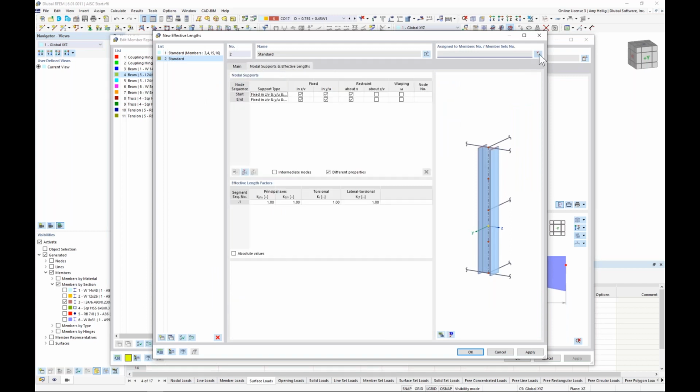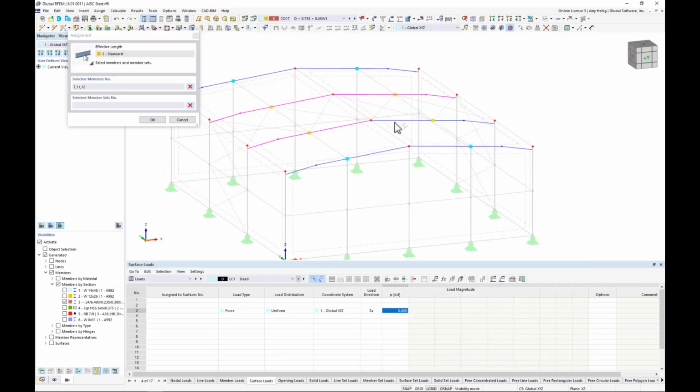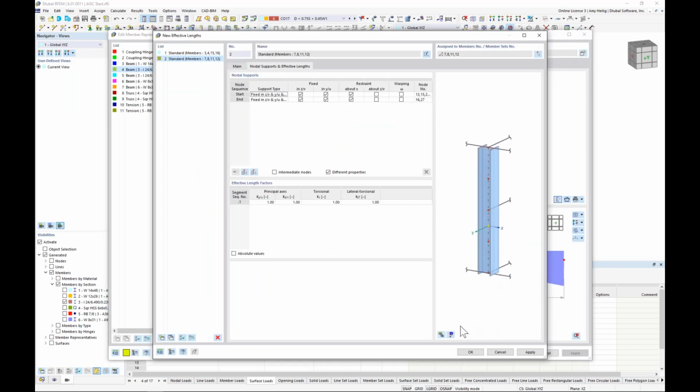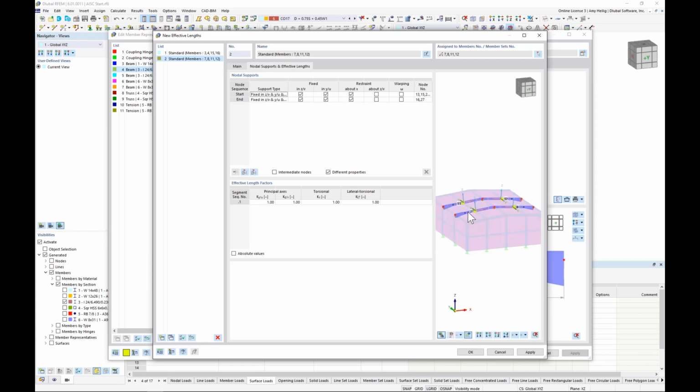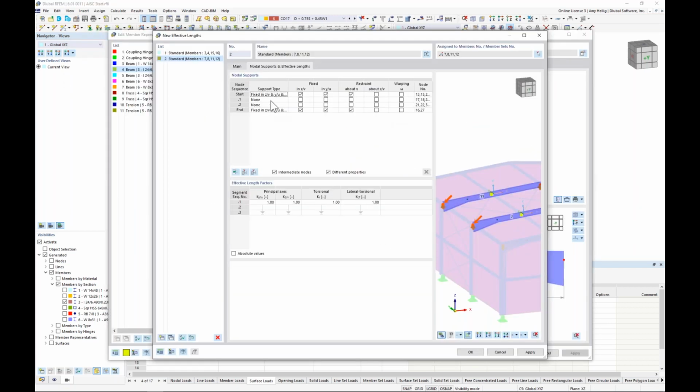And under the second tab, remember, again, I like to graphically select these. It's not necessary, but I think it's helpful in determining where you're at along the length of the member. So we're going to have the program automatically detect the intermediate nodes. Two additional rows are given to us here. Now this is slightly different. The first node, we can leave as default.